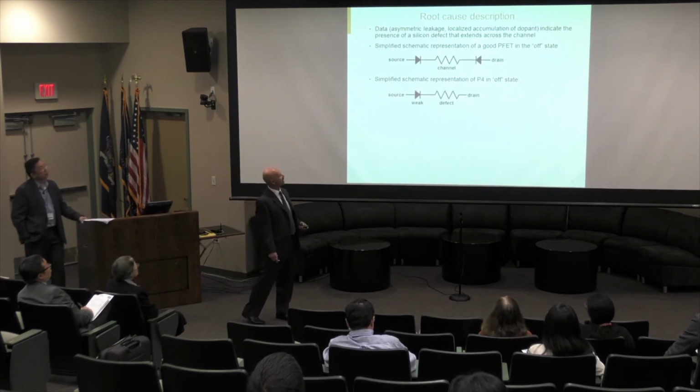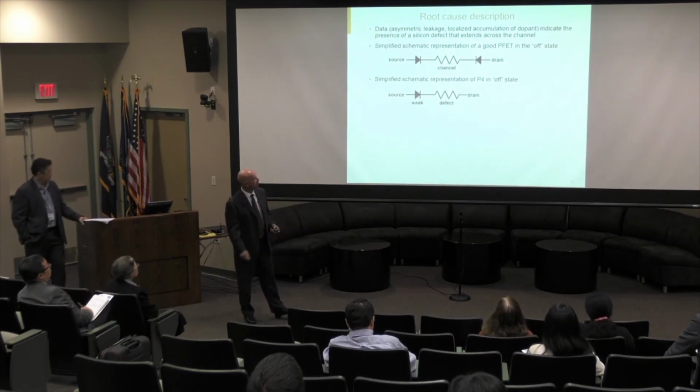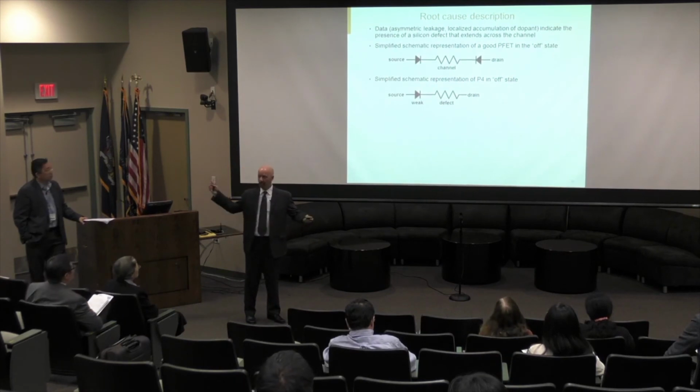And this is a description of what the actual root cause was. What it was, a silicon defect, which caused an accumulation of dopants, which resulted in a short circuit in that device. And now I will go to my concluding remarks.